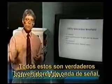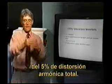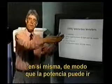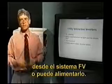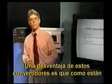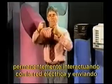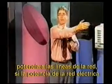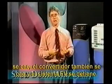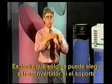All of these inverters are true sine wave inverters, putting out a waveform that has less than 5% total harmonic distortion. And they also synchronize with the utility waveform itself, so that the power can go from your photovoltaic system or can feed into your photovoltaic system. A downfall of these utility interactive inverters is that since they are interacting with the utility all the time and sending power into the utility line, if the utility power shuts down, the inverter shuts down, and your photovoltaic system typically shuts off.